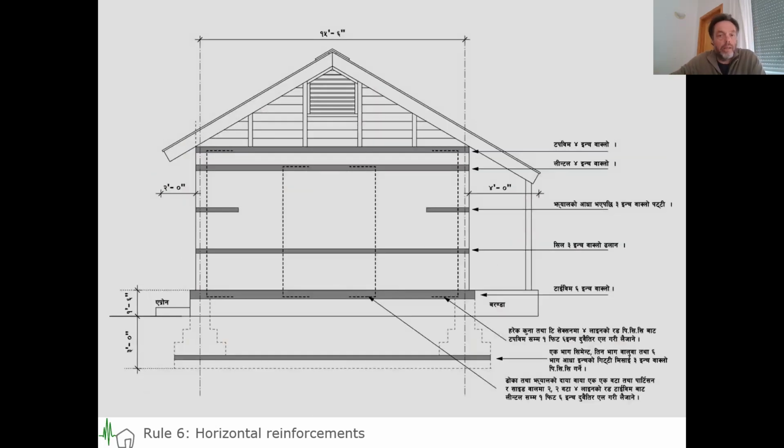So in our buildings, because we were in a high seismic zone, we did reinforcements at 5 levels. The first one is on top of the foundation. The second one is the sill beam, which is below openings. There is a lintel, which is on top of all the openings. There's a top beam, and there are stitches in the middle just to break the height here and create some extra break, so to speak, to avoid shear cracking in the corners.